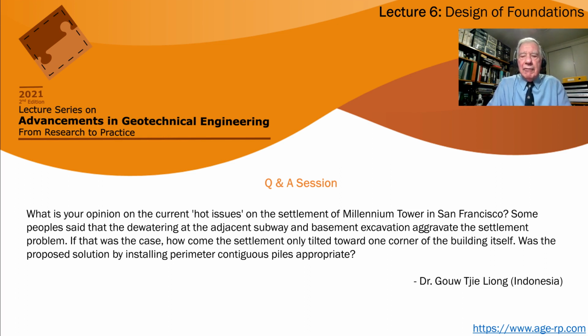And so if you're doing any drilling or whatever to try and put in additional piling, that will have an influence on the existing foundation system. So you must always be very careful in your corrective measures that you are aware of the risks and you take measures to mitigate those risks in the foundation correction.